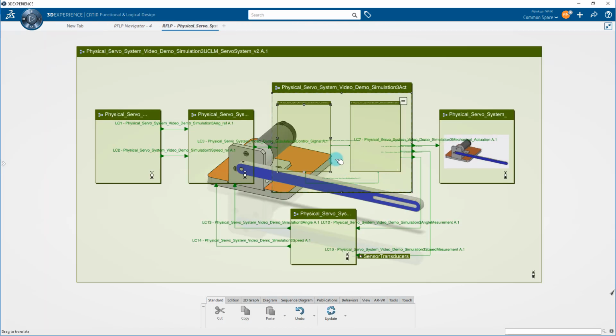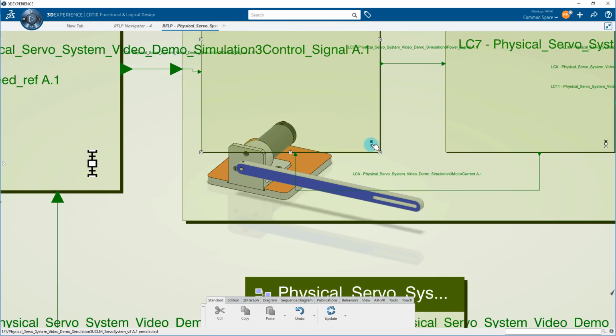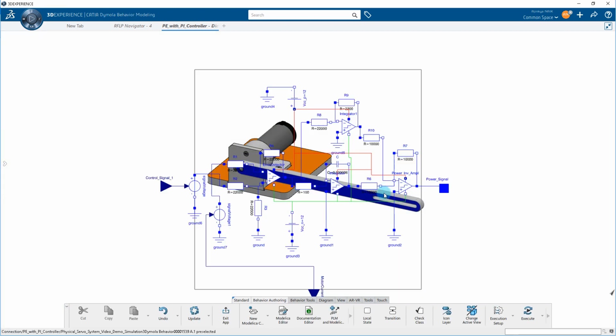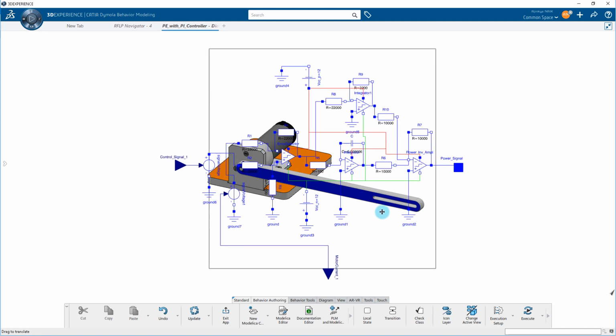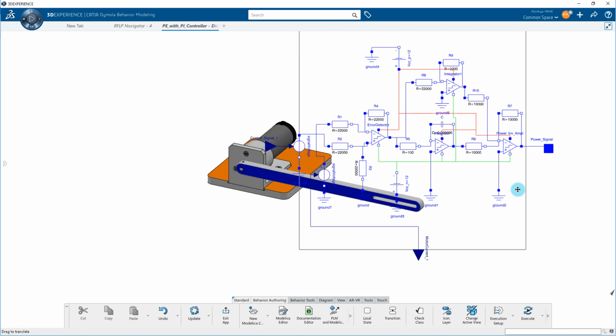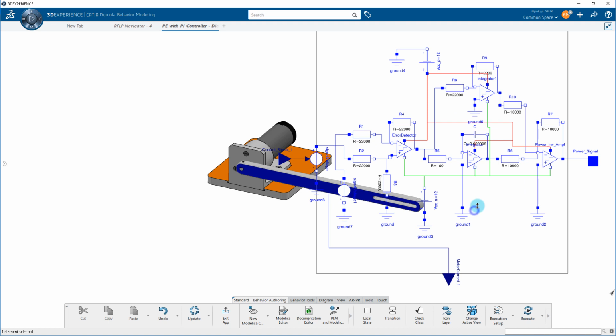We will now see the behavior for the power electronics block. We have given two behaviors to this block. The objective of the power electronics block is to adapt the voltage to the maximum voltage range of the DC motor, providing enough intensity. Because the power of the selected DC motor is very low, there are several technological possibilities: power operational amplifier, PWM, etc. Here a power operational amplifier working as an inverted amplifier with unit gain will be used.